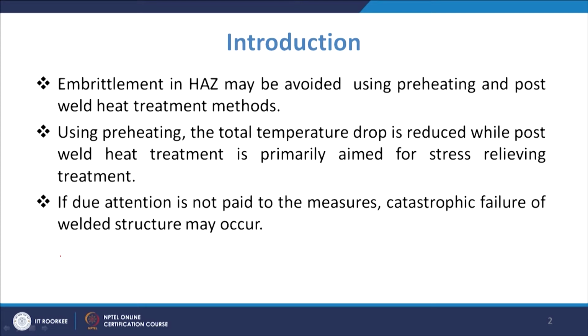Using preheating, the total temperature drop is reduced, while post weld heat treatment is primarily aimed at stress relieving. Normally, when you are not doing preheating, the temperature attained is very high, while the specimen where the heat is flowing is at room temperature.